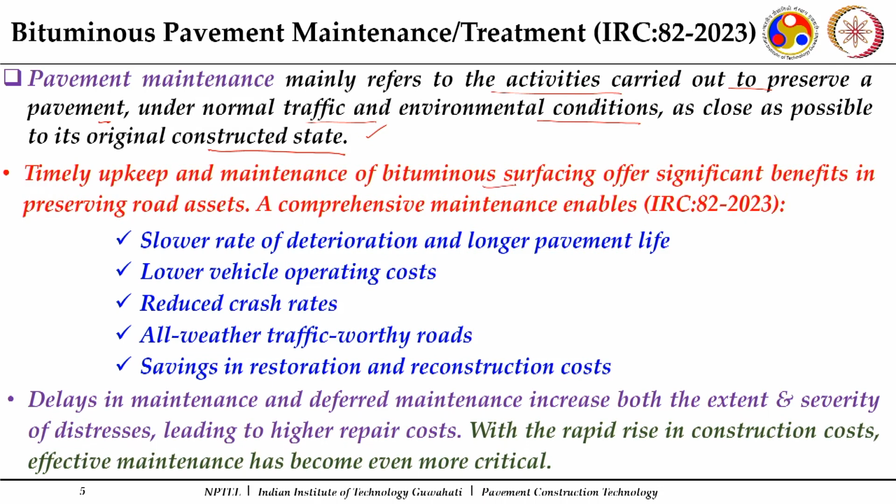Timely upkeep and maintenance of bituminous surfacings offers significant benefits in preserving road assets, because our transportation or our road structures are our assets. As per IRC 82 2023, these timely maintenance activities help us slow the rate of deterioration and give us a longer pavement life, lower vehicle operating cost, because you are able to keep the standards of our roads high, and reduced crash rates. If the surface is maintained to a good quality, good skid resistance, good smoothness, then definitely the chances